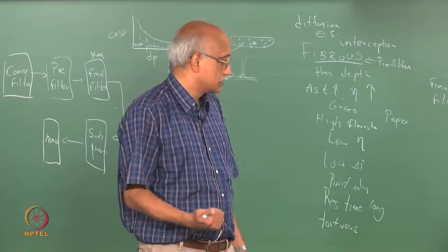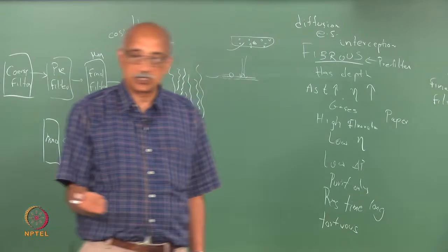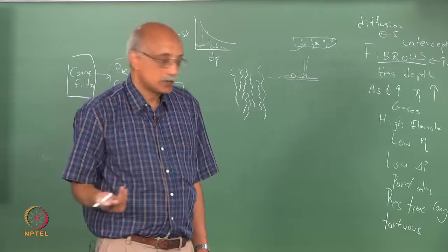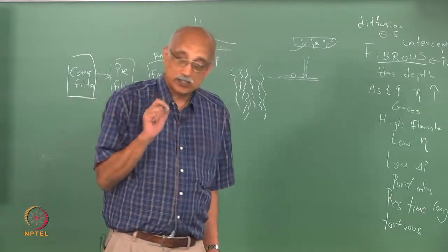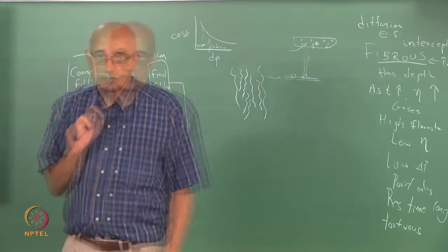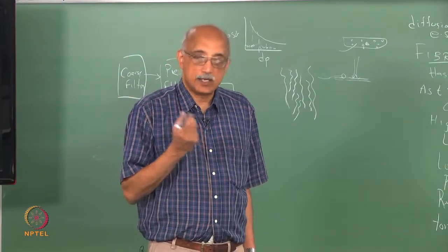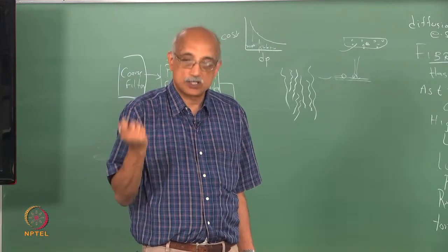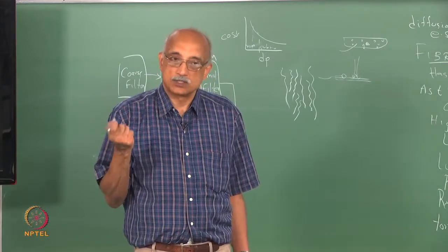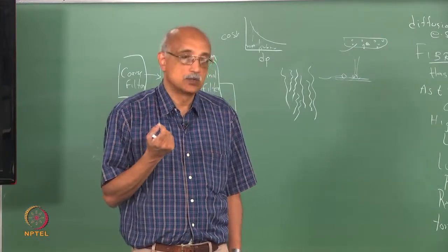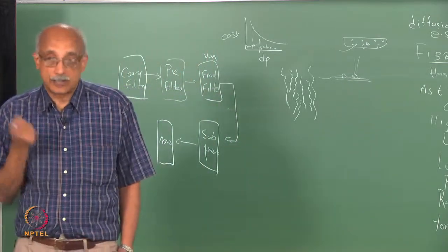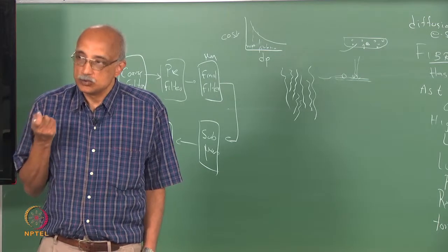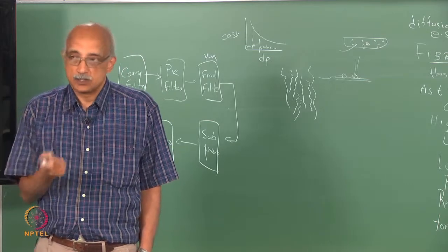As the volume fraction of fiber material increases, obviously the filtration efficiency increases. As the length or depth of the bed increases, filtration efficiency increases. As the diameter of a fiber decreases, filtration efficiency increases. So, if you can make a filter with extremely fine fibers, the capture efficiency tends to be extremely high. This is another reason why nanofibers are now being used, particularly in nano filters. In order to filter nanoparticles with high efficiency, you need fibrous filters that have nano sizes.